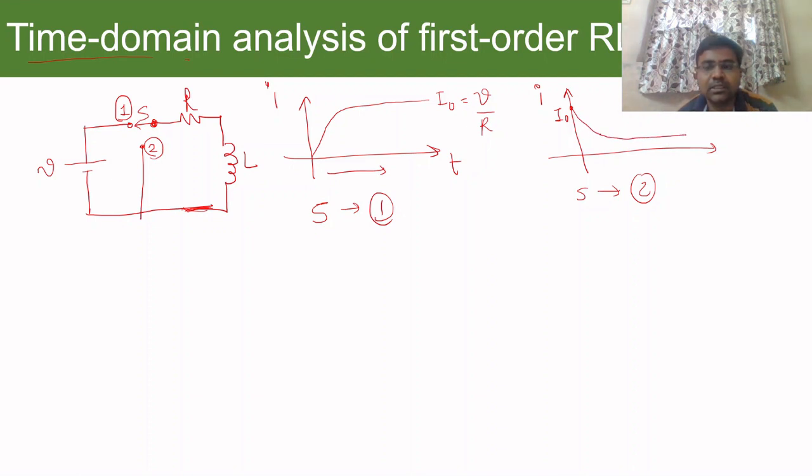So what are the dynamic equations that we need to understand? Firstly, when you connect a series RL circuit, there is some voltage drop across VR, and similarly we have some voltage across VL. If we apply KVL here, we can write V equal to VR plus VL. Now what is V? V is the source voltage. So this voltage gets dropped across R and L. That's why I have written V equal to VR plus VL.